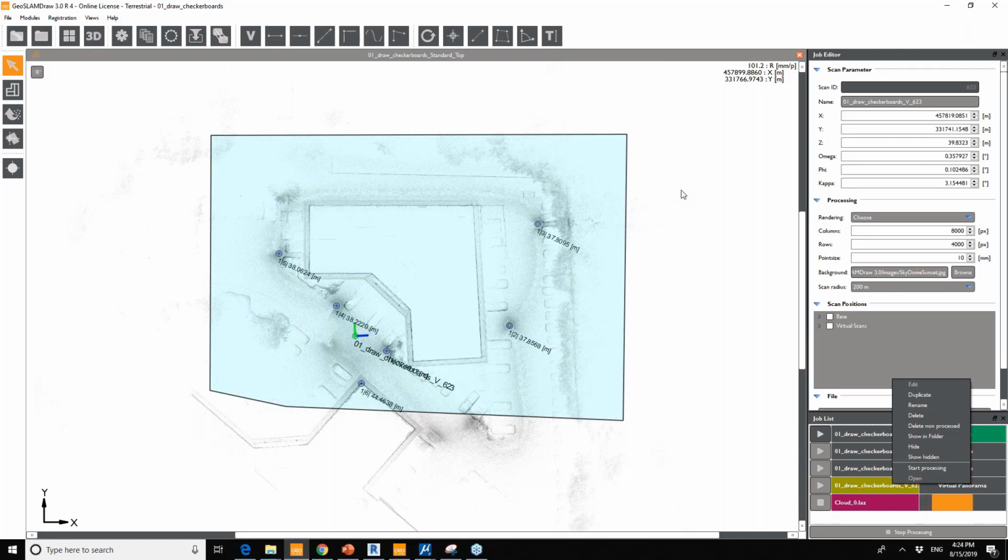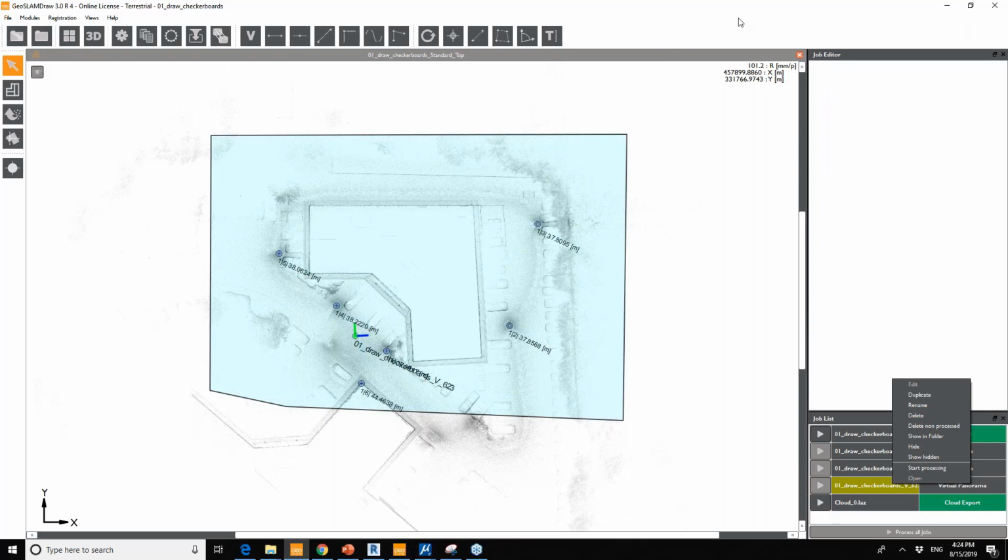Now, this was georeferencing using the targets, but if you have the RTC or the Horizon and want to use the reference plate, the points are actually saved within the trajectory automatically as you put the system static for 5 seconds over the points, like nails or small points that you cannot easily see in the point cloud.